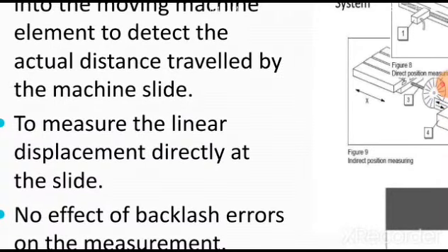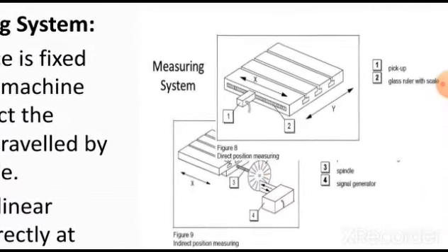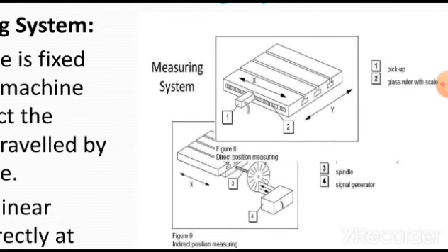So this is also one of the most important points. You need to understand the meaning of backlash. Backlash is a type of improper positioning. Whenever there is a mechanism where we convert rotary motion into linear movement, even if the lead screw or the ball screw is made to rotate, you are not going to observe the proper movement of a linear element or a table. Such a drawback or error we call backlash.